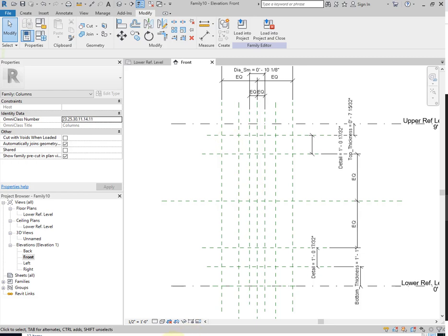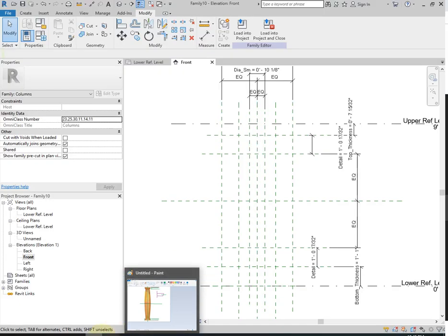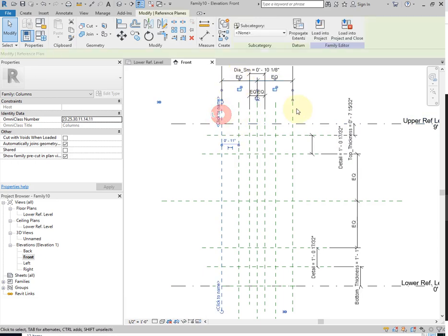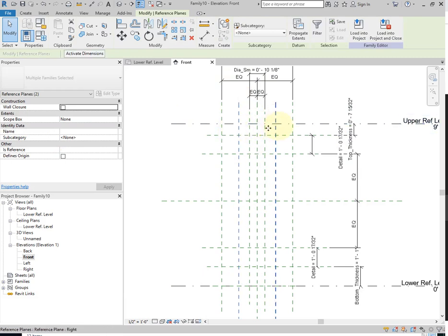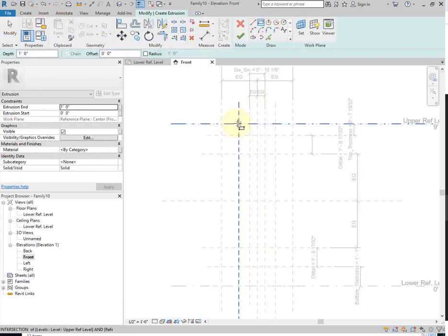So to start, I am going to create the top and bottom squared cap ends. And I can do that all from the front. Carefully understanding that the outside is your large diameter, inside's the small. So basically, my cap is going to go between the second inner ones and then up to the bottom and tops of each one. So I'm going to create an extrude. And I can create both extrusions in the same set here.